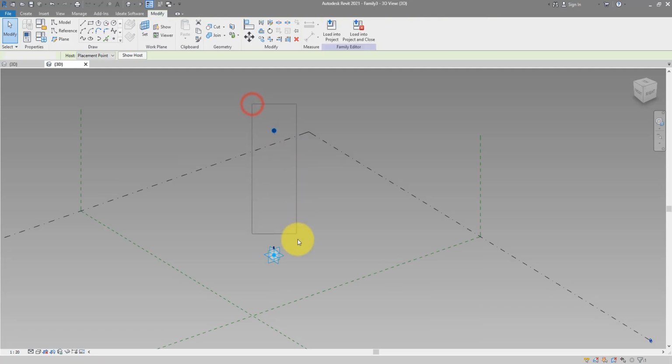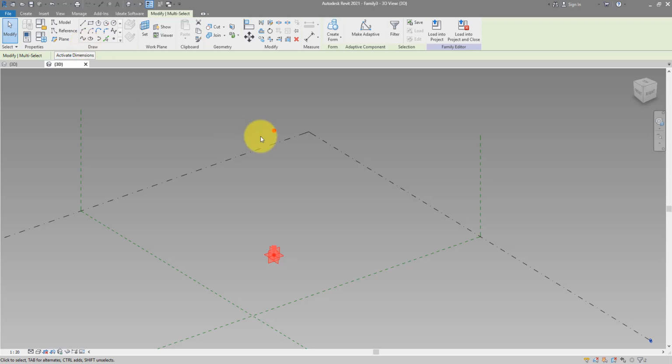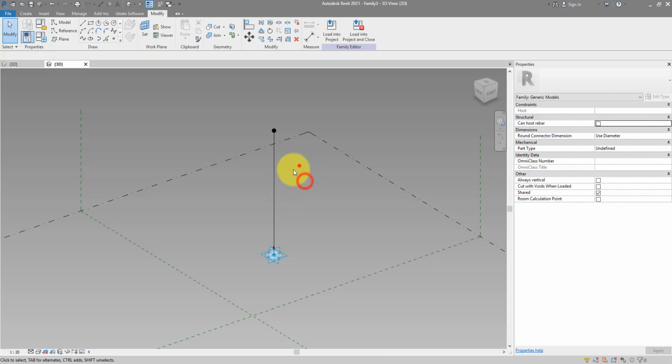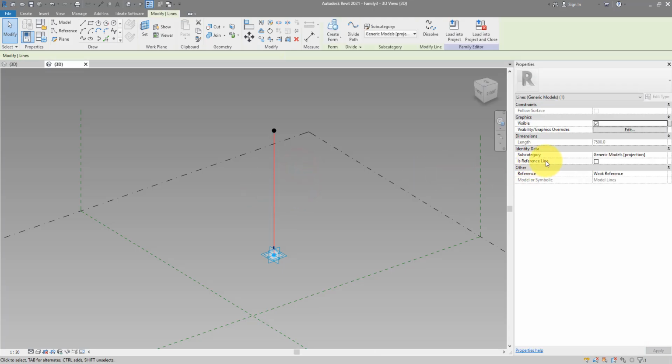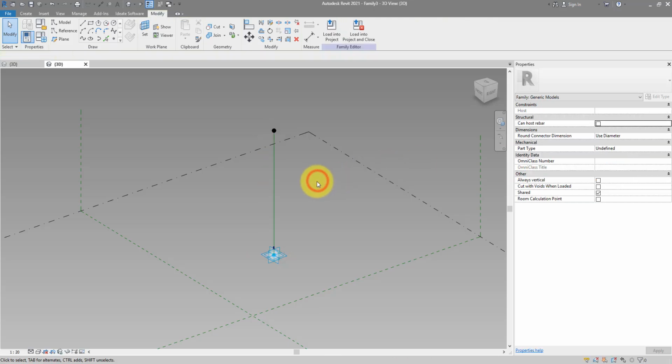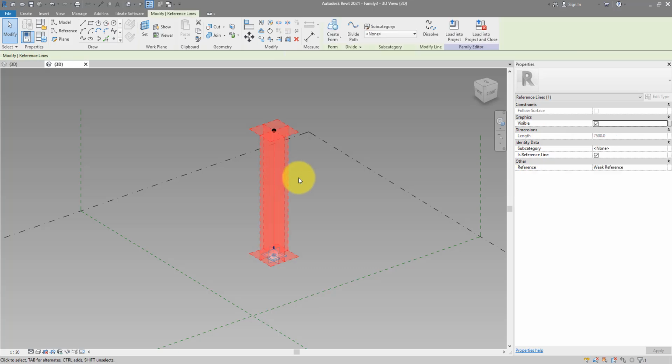Okay, it's time now for me to select them both and then make a reference line between them. We can do it by this spline through points tool. Turn on my properties window, get this line and make it into reference line. Ticking this box will do that. You know it's reference when it's green and it has those other planes surrounding it like this.